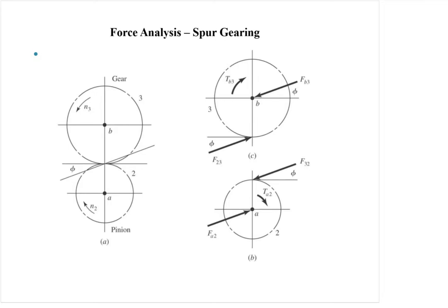So if you're having some sort of failure and you have some sort of wear pattern, it's important that you track that back to what you know should be the actual forces. And if you're getting a wear pattern that doesn't coincide with the expected forces, then you have to start looking for what unexpected forces could be causing that wear or early failure location.